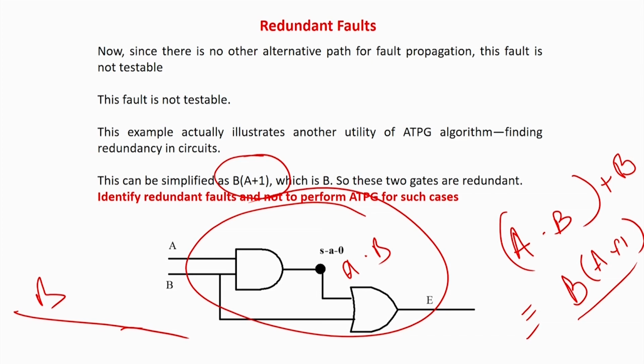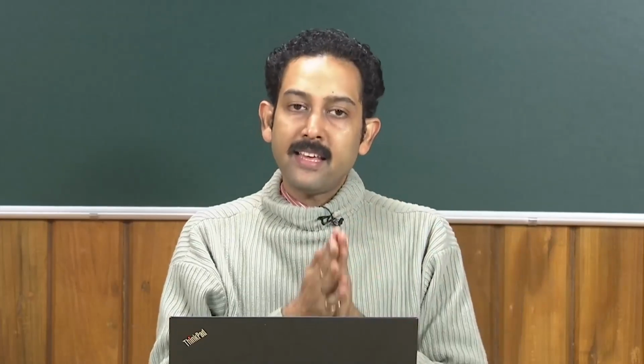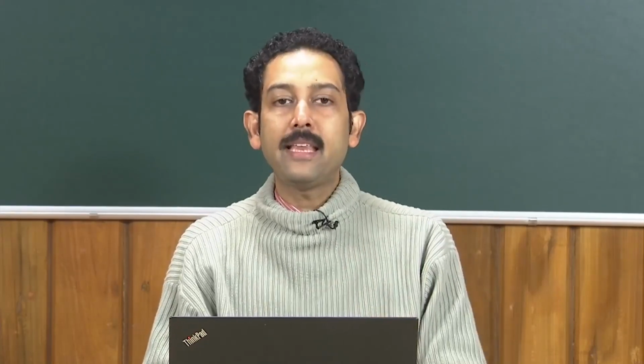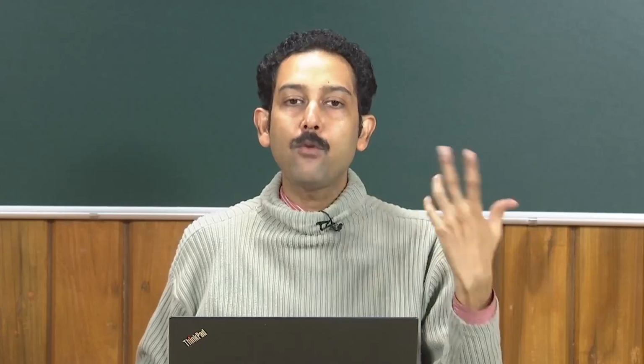So, that means this circuit is not an optimized circuit. You have put a lot of redundant gates. In VLSI design, sometimes a lot of redundancies are put in to avoid hazards and put buffering arrangements, etc. But somebody should identify the redundant circuits beforehand, because in a real optimal VLSI design, which has already been covered by Chandan sir in the case of design, generally we do not give any redundant circuits, because they do not do any job but eat up your area overhead. No automation or design tool will give you a redundant circuit.